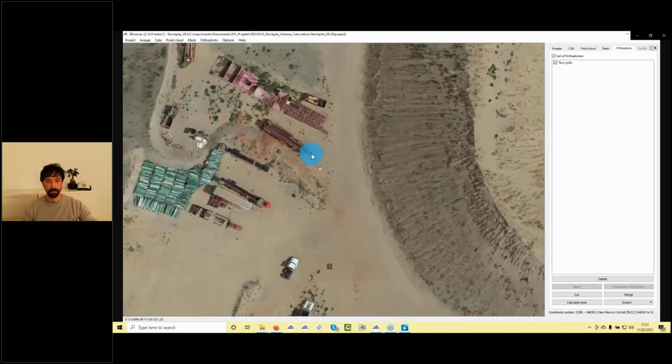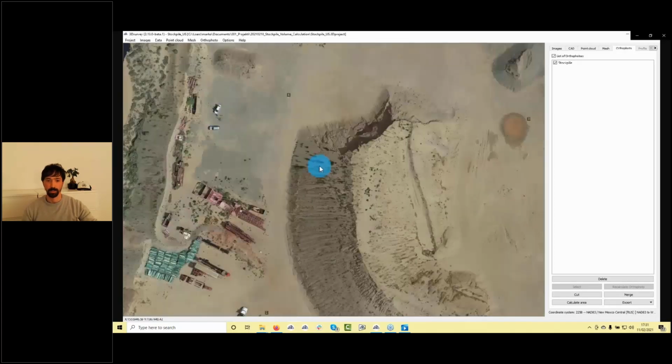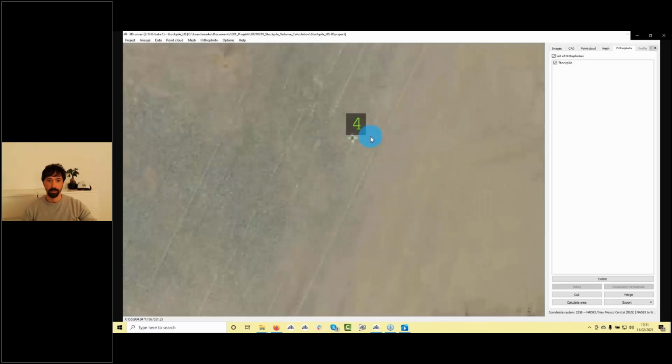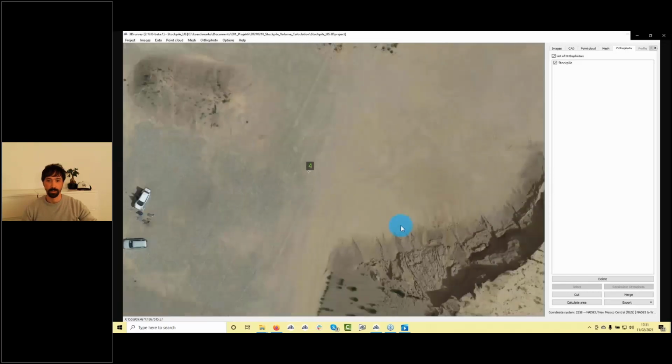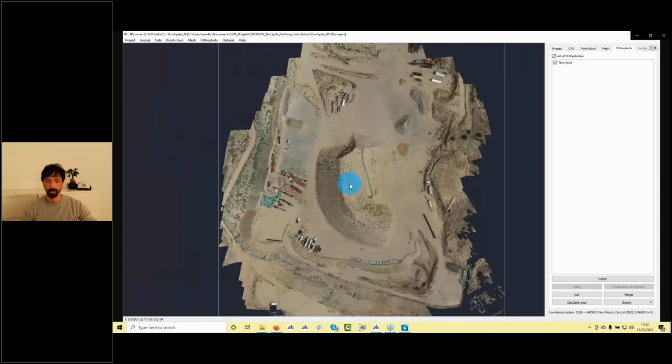So even if we have buildings or anything like that, roofs are on the accurate location. Here we can see our markers, ground control points, and we finish actually with the workflow presentation. From 2D images, we calculate accurate 3D textured model, and now we can also see our true orthophoto. Of course, it's always great to save your project after you finish it and maybe generate a general report.